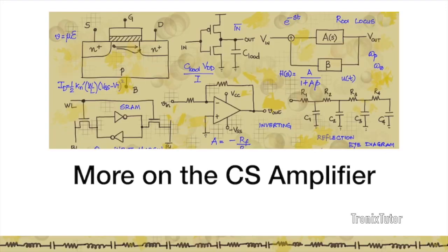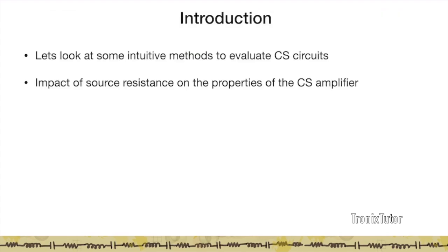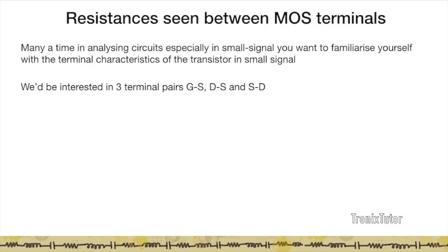Hello and welcome to this video where we'll discuss a little more on the common source amplifier. In this video, I'll discuss some intuitive methods to evaluate common source circuits, and then we'll look at what the impact of the source resistance would be on the properties of the common source amplifier.